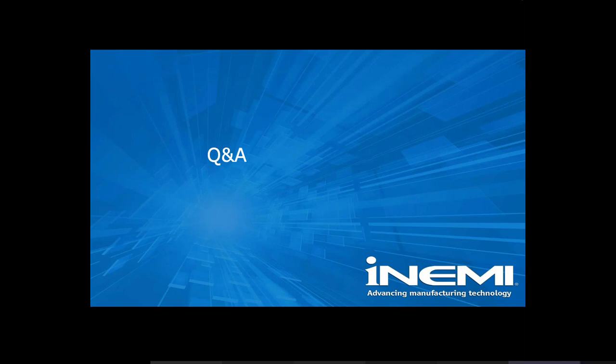So the plan is to include the AOI machines' capabilities and status in the survey, as we mentioned that step 1 is to conduct the industry survey. The survey will ask about the capabilities of 3D, whether it is possible to capture height variance or width variance on the 2 micron, 1.5 micron design rules and patterns.